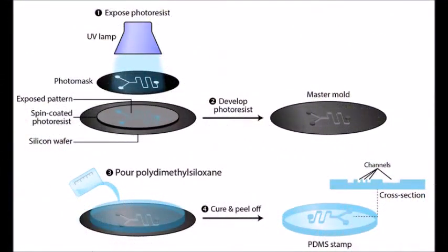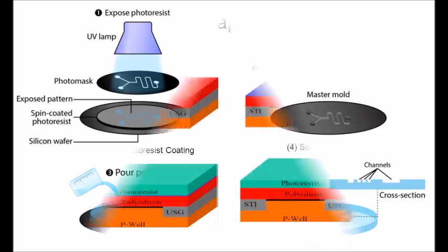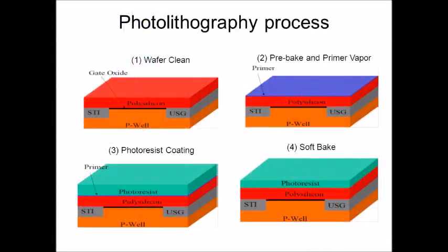Another way to create auxetic materials is to use photolithography. Photolithography takes advantage of the difference in solubility when light is exposed to a photomask. By etching a design on the photomask, chemicals can be used to dissolve a region of the structure while keeping other parts of the structure intact. This can be used to make repeating structures on a microscopic scale.